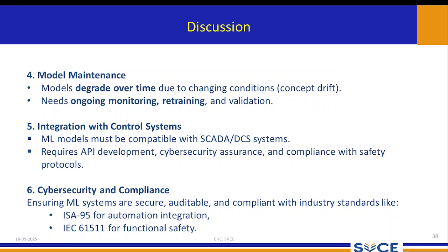What are the key features and benefits of DCS? Distributed control: functions are distributed across multiple controllers, improving system reliability and making it easier to manage large complex processes. Real-time monitoring and control: DCS provides real-time data collection and processing, enabling operators to monitor and control the process effectively. Enhanced safety: by automating critical control functions, DCS can reduce the risk of accidents and improve safety. Improved efficiency: DCS can optimize the process, reduce energy consumption, and increase productivity.